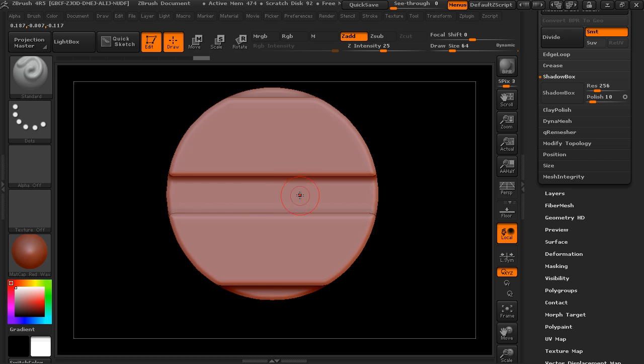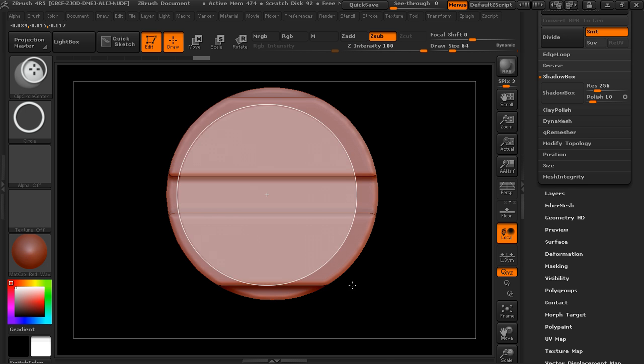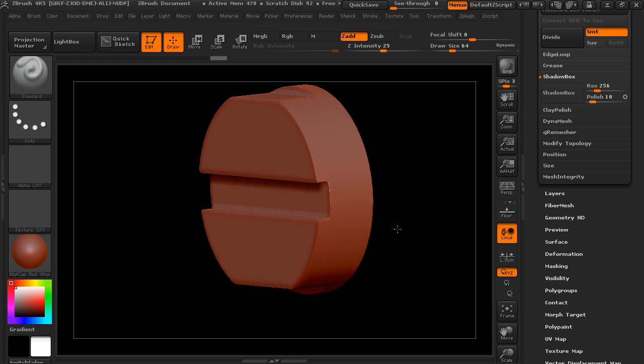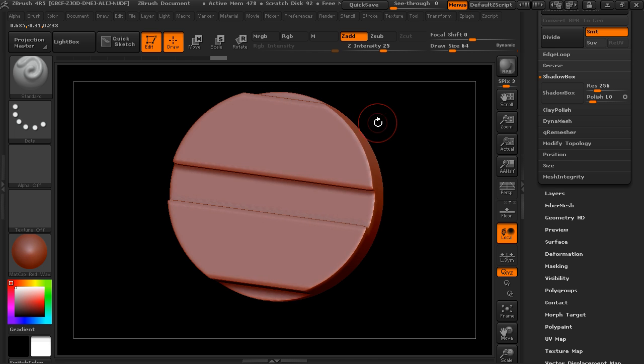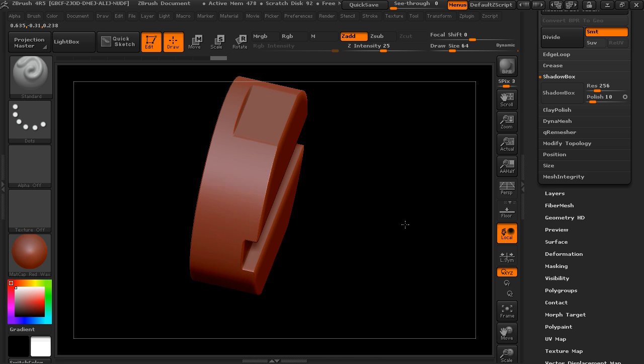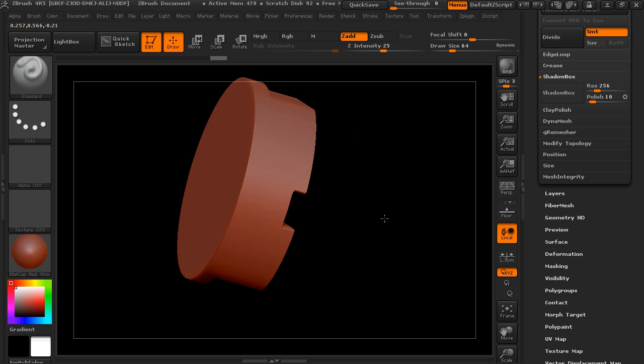And what that will do is smash everything down to whatever we have defined. So I can bring out this clipping circle, and I just want to bring it right out to the edges. I'll kind of move it around, and then release. And you can see that clips everything down, smashes all those polygons down to align with that particular circle. So we've created something that's very, very smooth.